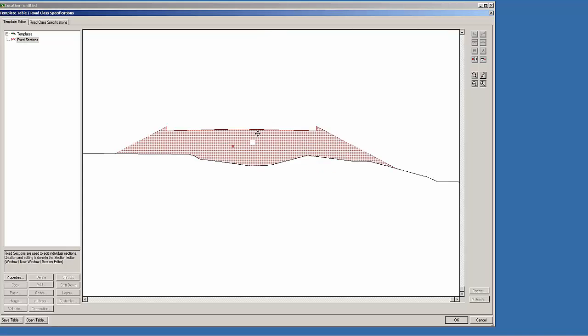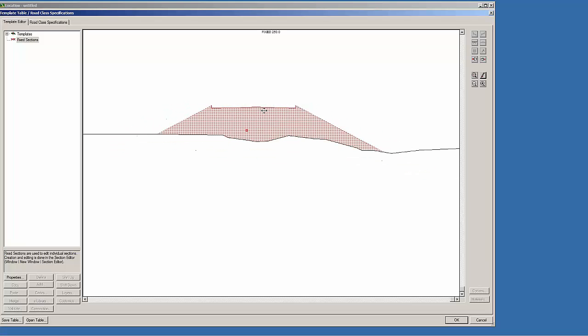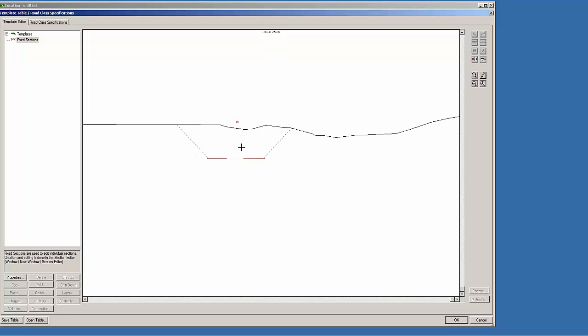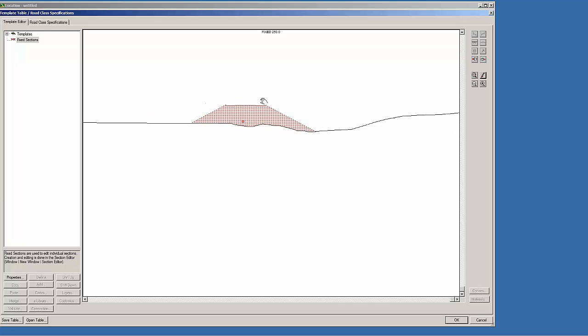And you can see that there's some smarts in here that actually say, oh, I'm just going to extend that last slope. Where it doesn't do well is when you get down here and it thinks, or it should have a ditch. Well, it doesn't have a ditch. It's not smart enough to figure that out from just the simple subgrade surface that it had, so it's extending it. Again, if your purpose is just to get a quick optimization done to see what you're working with, you may accept this vertical movement as a good enough approximation.